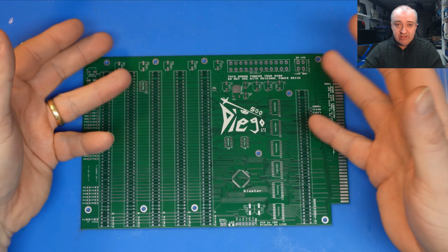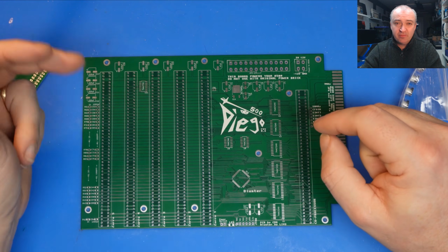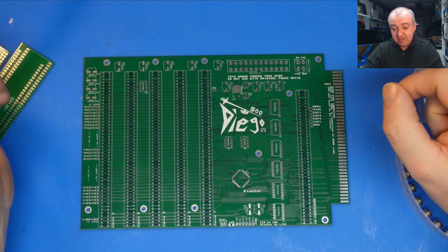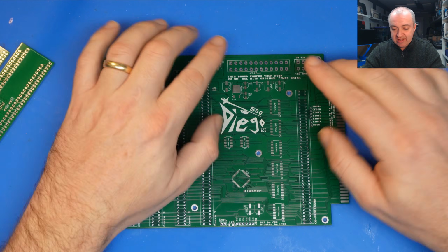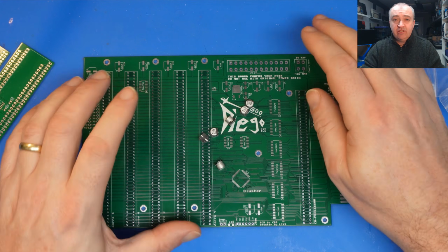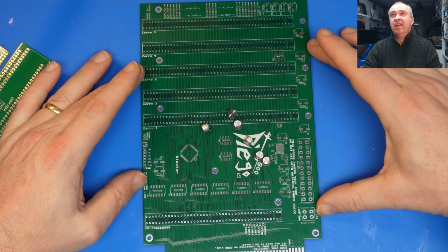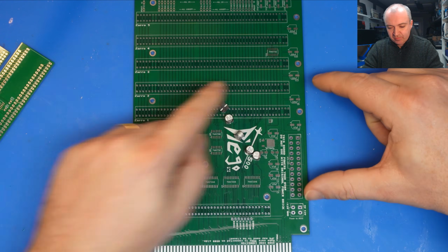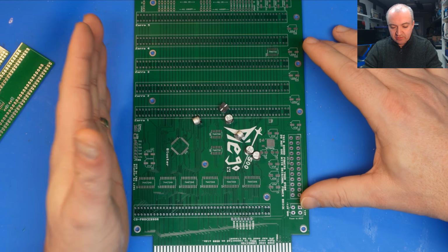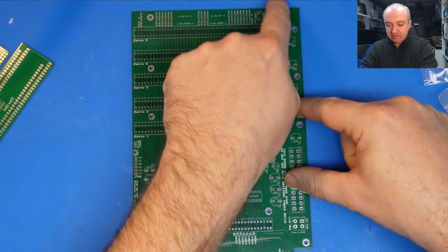All the components are labelled. I tried to label everything with what the component is in terms of its component number, but also the resistance or the capacitance of whatever said thing is. All of those values I have stuck underneath the component just to try and keep the board as tidy as possible. And the other thing that I've done is just try to keep all the capacitors in the same orientation as far as is possible. All of these electrolytics are all facing so that the positive side is towards the bottom of the board, although these ones, the positive side is to that end of the board.